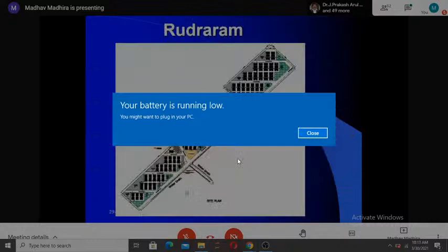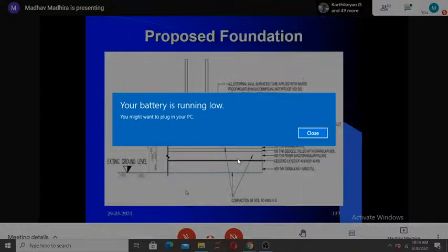We had another major project where they had to build 2-bedroom apartments very close to, again, the coast, and the whole area was highly soft and waterlogged. Originally, they thought we'll go for pile foundation, which became very, very expensive. It's not possible. So then they went for reinforced foundation beds. This is the design we provided.